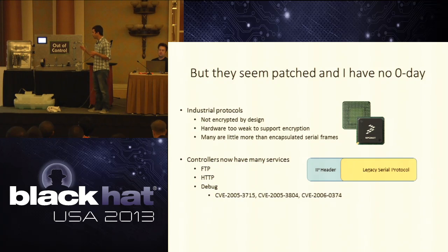Okay. So there's a couple of different things that we can do with the controller. One thing is that we can actually do binary exploitation of it, traditional buffer overflows and stuff like that, because a lot of these guys don't have the protections that you would see in a normal Windows machine, such as DEP and ASLR. These are just really old, simple machines. But what we want to do is we want to actually go after the protocol itself. We actually want to build a packet to tell the controller to drive its I/O without actually modifying the logic, just telling the logic to essentially be quiet and drive those signals ourselves.